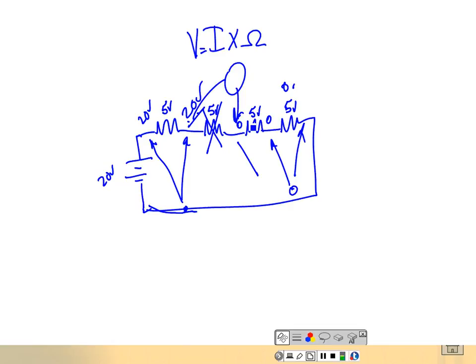So what we do is we clamp on, put our common on L2, and we start moving across things. And if I go across the coil, I got 0 volts on this side, 0 volts on that side. That means that coil is not open, right? Because if it was open, it would do what? It would drop the entire voltage. Okay, y'all understand that? So if something's in series, if it's open, it drops the entire voltage.